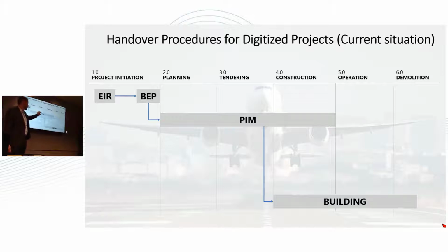We have a really nicely optimized building, as we saw from Christoph. Everything has to stay in place, otherwise it's not working, because the design has such high accuracy. When someone on the construction site did it in another way, nothing works anymore, and you lose everything. For that reason, it's really important during construction to have regular laser scans, several times, to get control of the construction site.